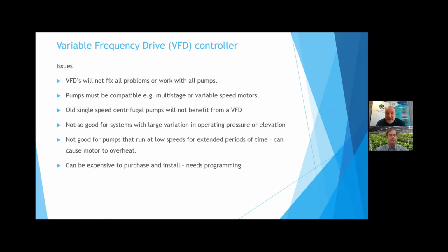As I just said, if that pump is not appropriate, then you may have to replace your pump. VFD drives or VFD controllers can be expensive, so you don't want to fork out $5,000 to put it onto a pump only to have your pump blow up a couple of weeks later. And besides, you can buy combined pump and VFD packages that are much more economical to purchase and install.